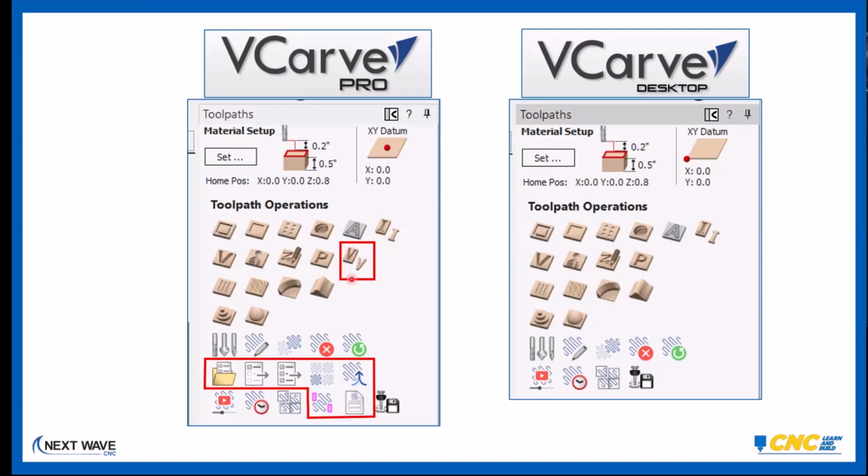Now, that just showed up in version 12, and you do not need that to actually do VCarve inlay. There is a way to use the standard VCarve toolpath to also do it. So if you want to do that without the Pro version, there are techniques out there available. If you have an interest in that, drop me an email. I also have some information on that. But the new tool is quite handy if you do have VCarve Pro.